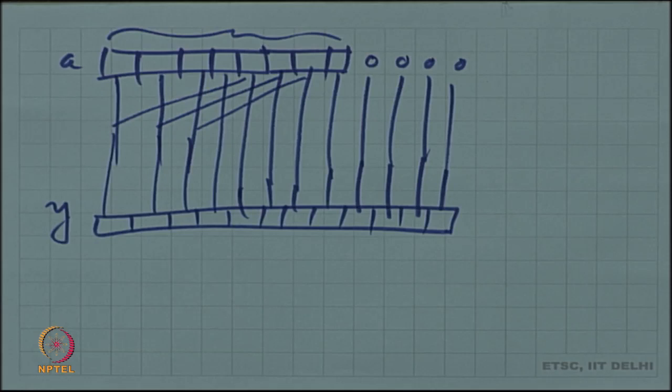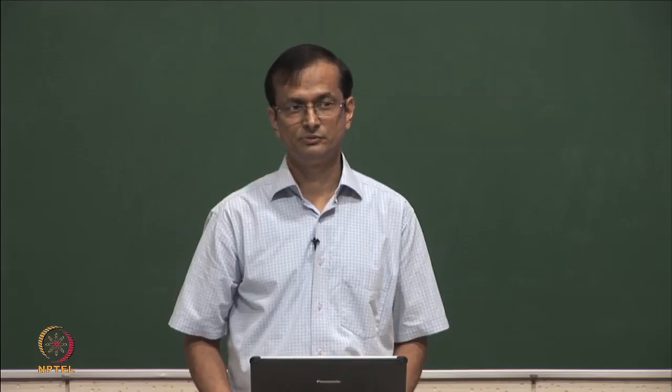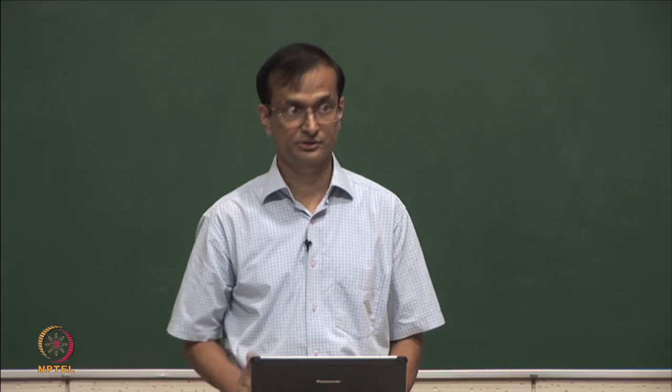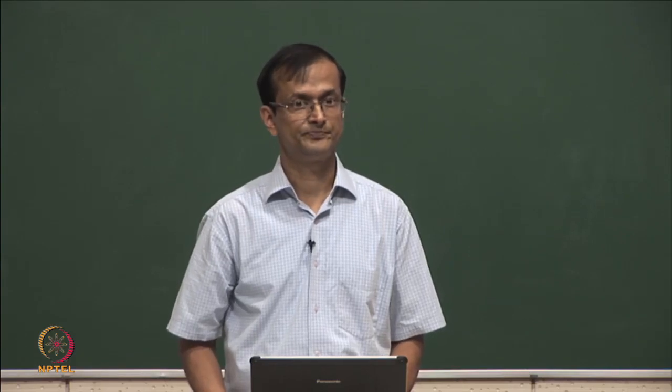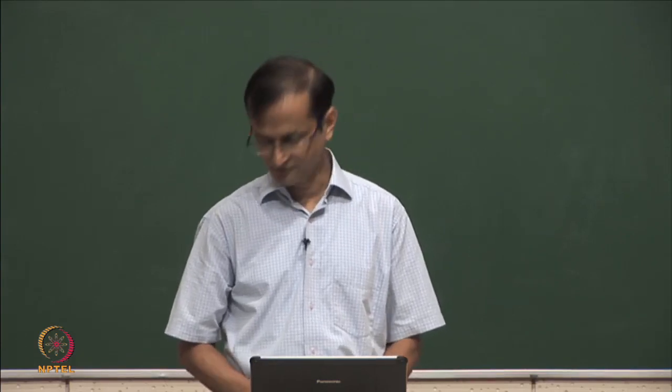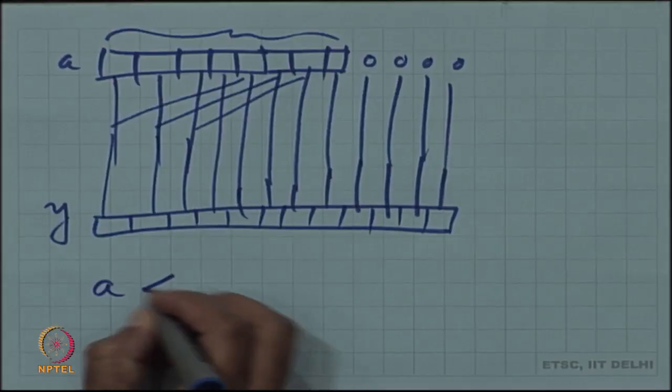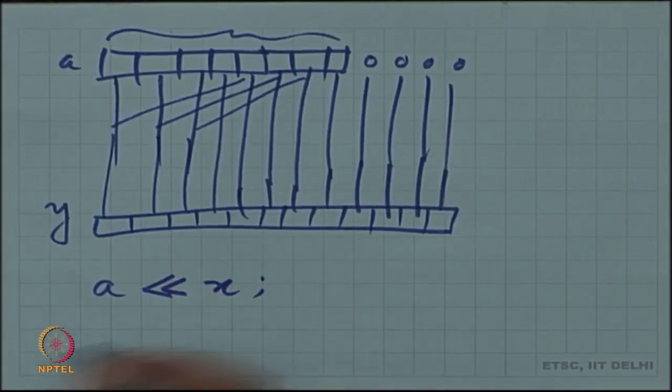A shifter circuit, in general, you have to instantiate when? For what kind of expression will you actually need to instantiate a shift circuit? Yes, if I had A left shifted by x, then you need a proper shifter circuit, because only at runtime do you know how much to shift it by.